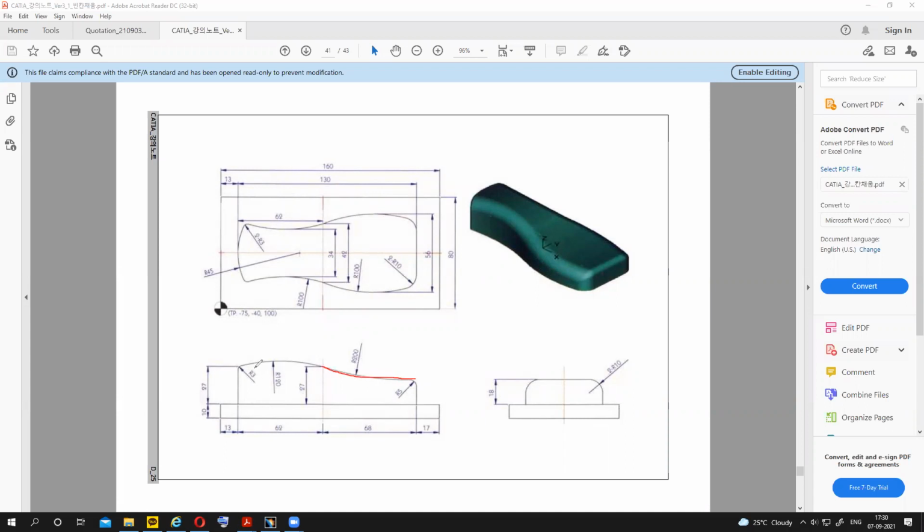So this R3 you can give later after finishing everything. Use fillet, 3D fillet, okay? So right now I cannot give the corner because I just draw arc, I didn't draw this line, right? I cannot give. So we can give that one later. Similarly, R5 also you can give that later. And here R200, okay?